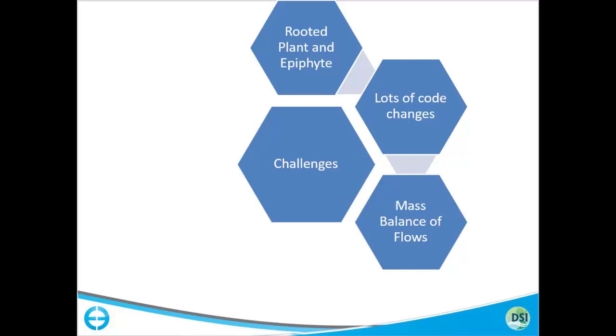One of the things we worked on was improving the dynamic time stepping in this model, and volume balance or mass balance is always important when you have flow boundaries on top and bottom, because if your flow is not balanced, you are going to have either a sharp decrease or a sharp increase in water surface elevation, depending on whether you have high inflows or low inflows into the system.